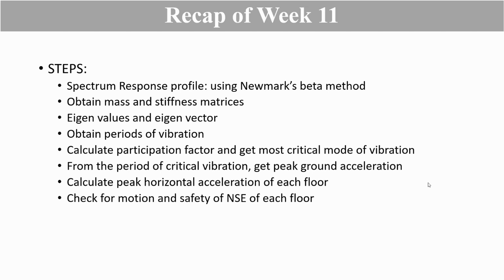So how to solve? Firstly, we will form the response spectrum for the given ground motion. This will be done by running two for loops, one changing the time period, and within that, one changing the time step for each time period and recording the responses. Then for each time period, we get the maximum response, and these maximum responses are clubbed together to form the response spectrum. This is something we have seen from week 8 of the course.